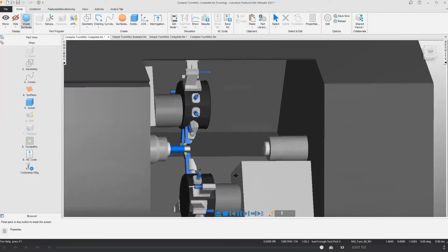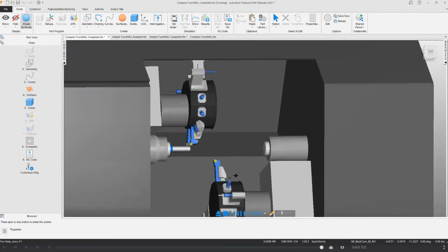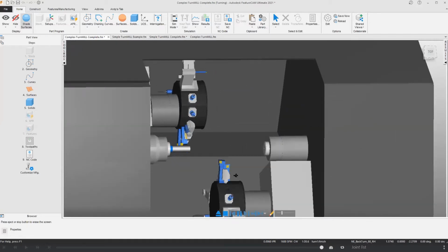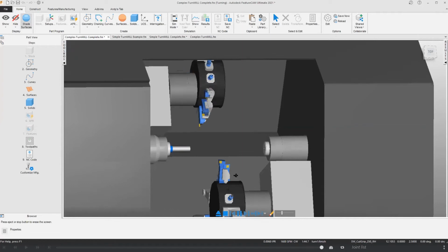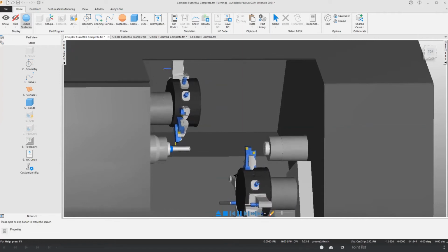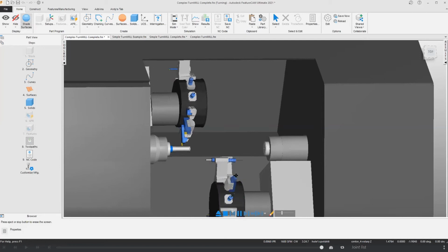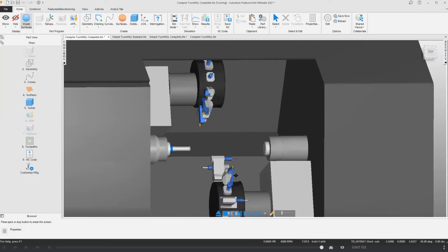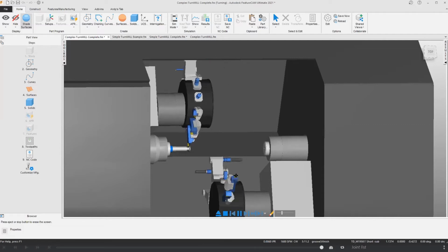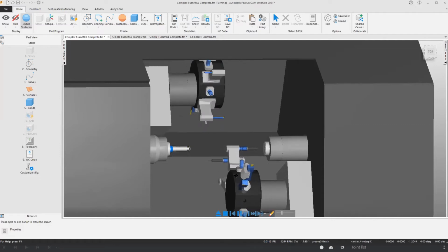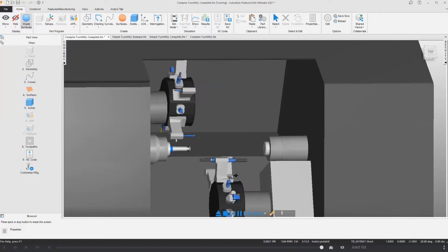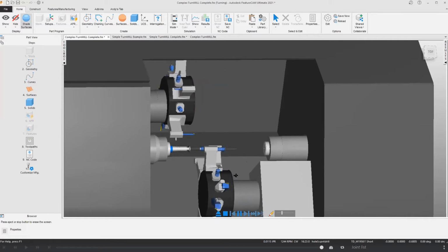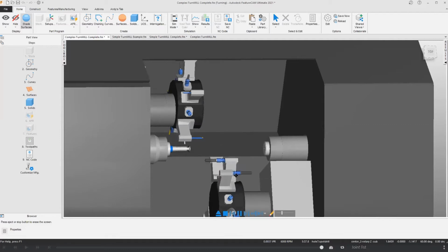So we see a machine simulation where more than one tool is being used at all times. Currently, the sub spindle is empty the first time through the simulation. That would be true the first time you ran the part, but this part has been synchronized to split up the operations among the multiple turrets and spindles in order to give you that efficiency and all those items that Eric mentioned to make productivity in your shop better.